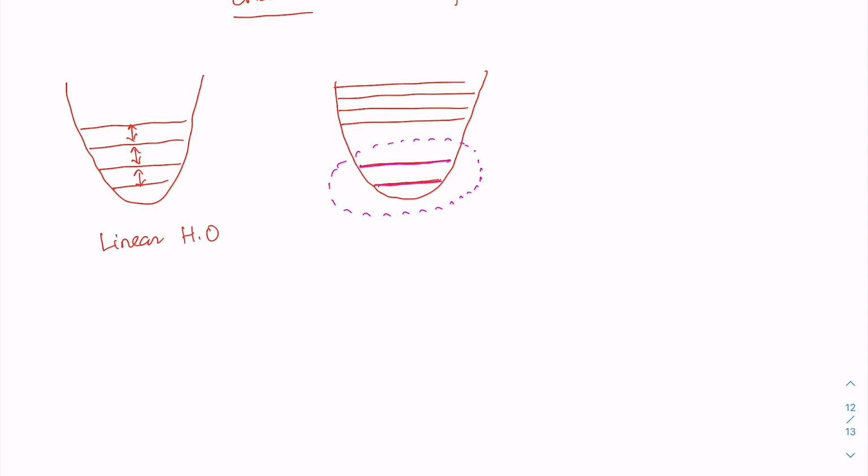In fact, when a circuit is composed of a Josephson junction, we know that the Hamiltonian, which we discussed earlier, has two parts. One is the charging energy part, that is Q squared by 2Cj, and the other part is because of Josephson tunneling, which is generally written as minus Ej cos phi by phi 0.